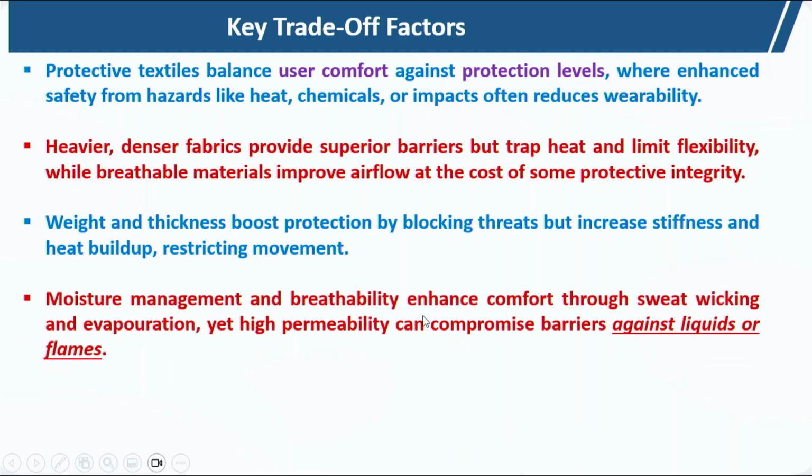Moisture management and breathability enhance comfort through sweat wicking and evaporation, yet highly permeable fabric compromises the barrier against liquid and flame. So these are the trade-offs, and we have to optimize the design.